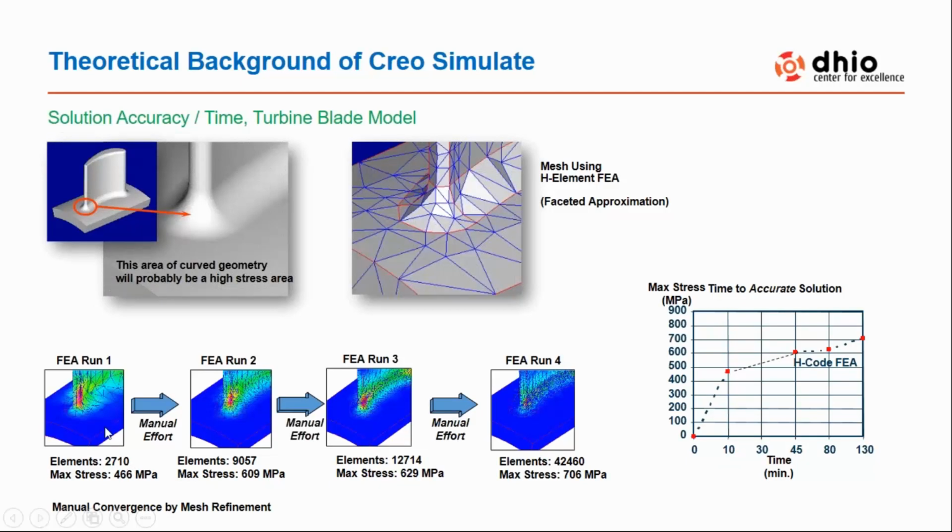We call it as mapped mesh. So the elements near to these characteristic curves have been increased from 2,700 to 10,000, and the corresponding stress values. Similarly, I will be increasing the mesh size near to the characteristic surfaces. After that, I will be checking the maximum 1 mesh stress, and I will do the mesh convergence. This is what we call mesh convergence.